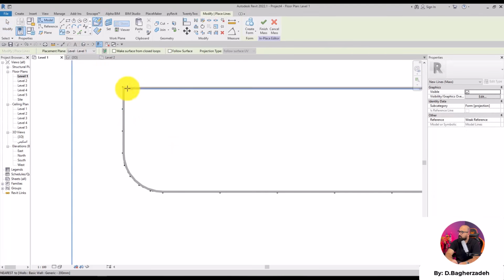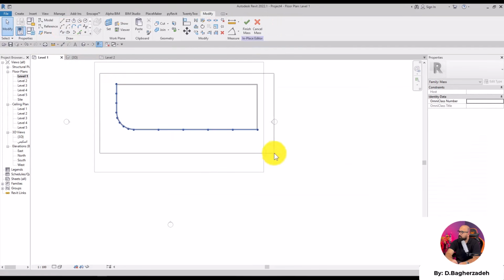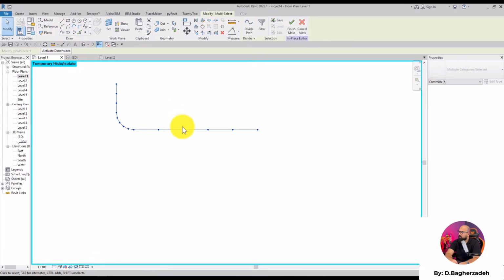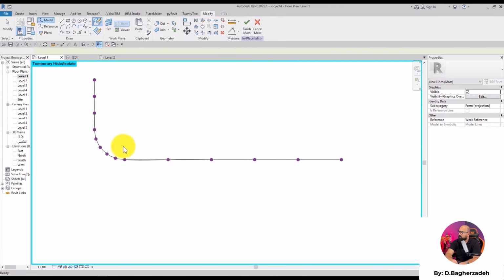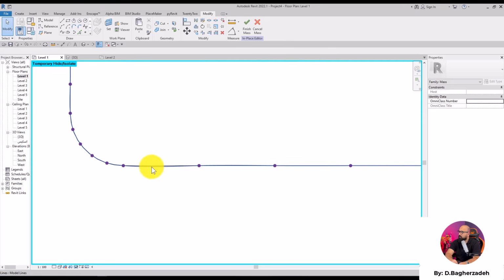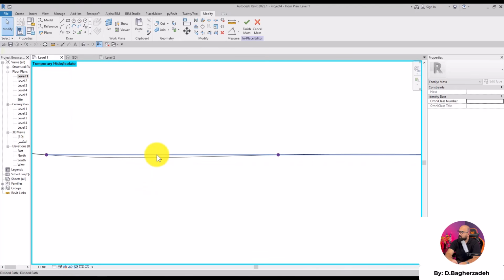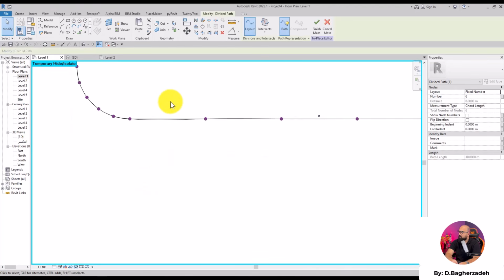Now, next up, we can use Spline Through Points. Before that, let me just isolate this line here. Here we go. Now, as I said, select Spline Through Points and start specifying all of these points exactly on this line here, so that the line that we're going to get later on would be completely one component. Alright, now guys, we have 2 lines here. I need to go ahead and select the lower one, which would actually be the reference one. Okay, I can select it and then remove it.